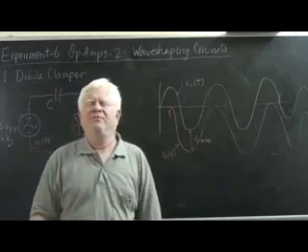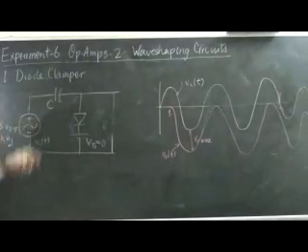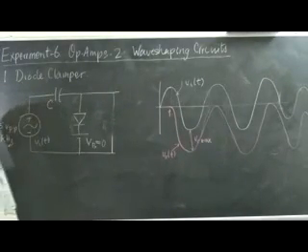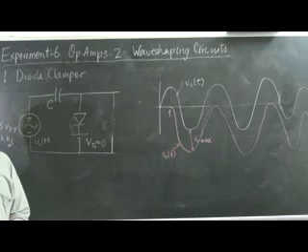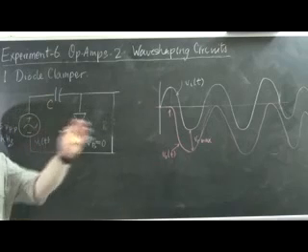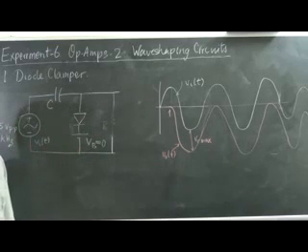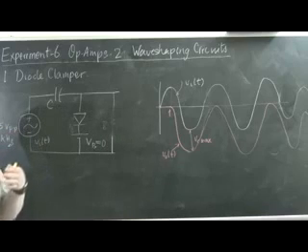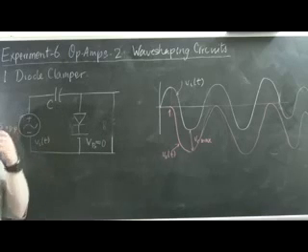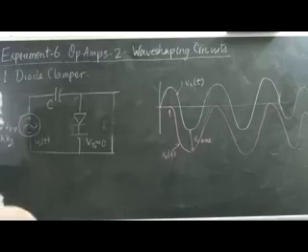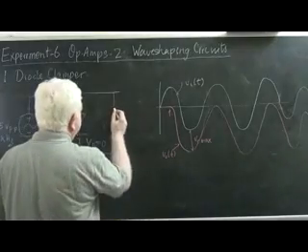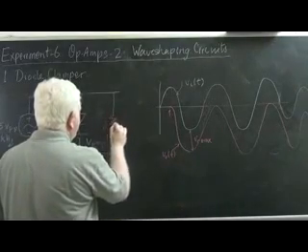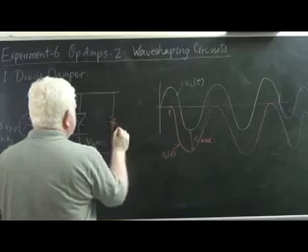If we really want that to happen, we ought to somehow give an opportunity for this capacitor to discharge, though only very slowly over several cycles of the input signal. The capacitor should be able to discharge and thereby adjust itself to large scale or long time changes in the input signal. This is the purpose of having this resistor over here.